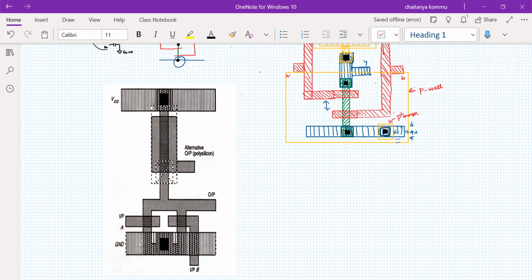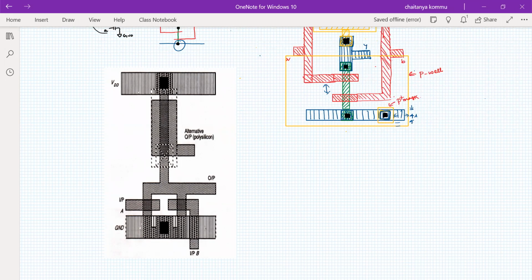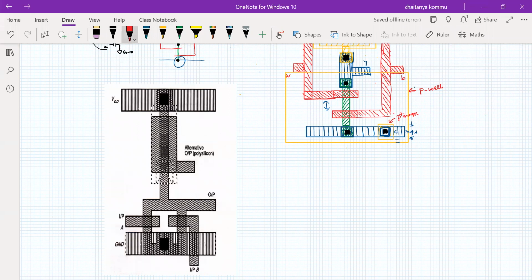As we know, this is VDD, right? So this is VDD. What is the length that they have taken here? The minimum is 3 lambda, but they have taken 4 lambda. Here also they have taken 4 lambda metal 1. Now, this is the depletion mode type of transistor. The diffusion is extended towards this side, and this side also. So the output is taken here.